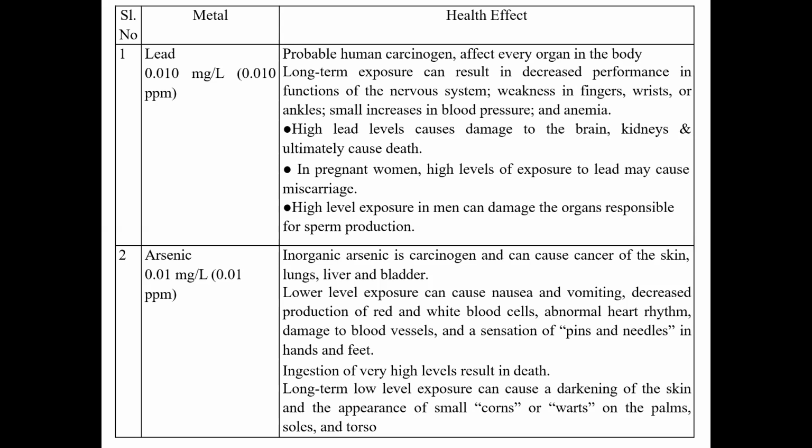And arsenic, what is its health effect? Arsenic: 0.01 mg per liter or 0.01 ppm. Inorganic arsenic is a carcinogen and can cause cancer of the skin, lungs, liver, and bladder. Lower level exposure can cause nausea and vomiting, decreased production of red and white blood cells, abnormal heart rhythm, damage to the blood vessels, and a sensation of pins and needles in the hands and feet.